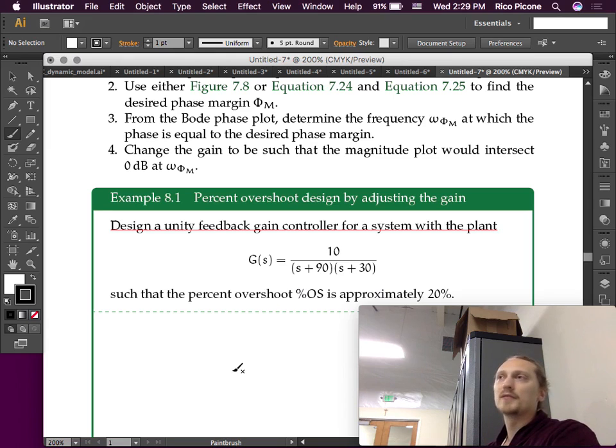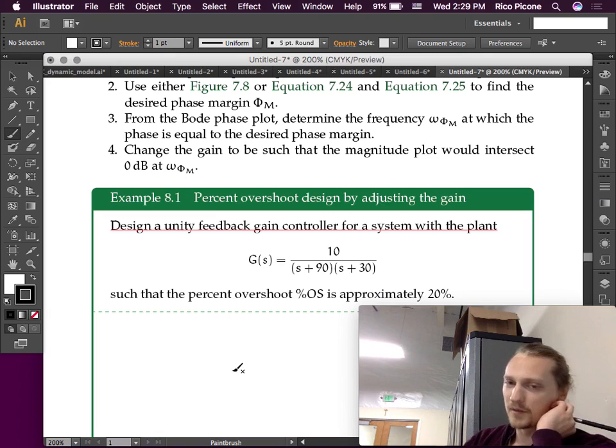So that's a really small DC gain. But it does have this gain term of 10 in the numerator that we need to watch out for. Sometimes when we refer to the gain of a transfer function, we're referring to that DC gain value, and sometimes we're referring to whatever that numerator is. It just depends on the context. We just have to be aware of the two possibilities.